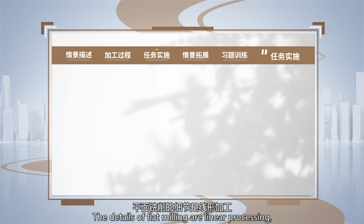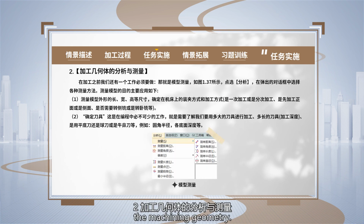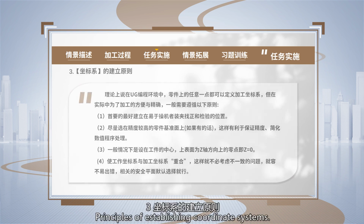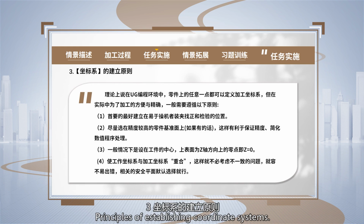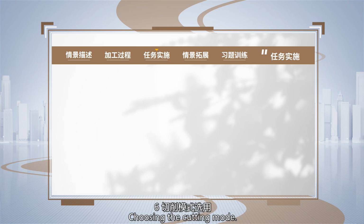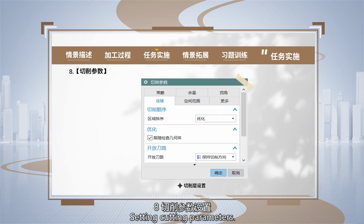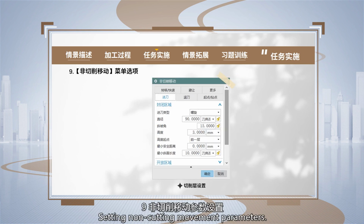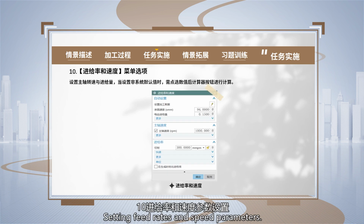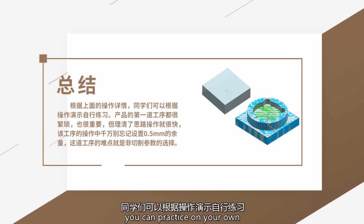The details of flat milling are linear processing, which involves checking the machining geometry, analyzing and measuring the machining geometry, principles of establishing coordinate systems, selecting the machining range, setting the boundary geometry, choosing the cutting mode, setting cutting layers, setting cutting parameters, setting non-cutting movement parameters, setting feed rates and speed parameters. Based on the above operational details, you can practice on your own according to the operation demonstration.